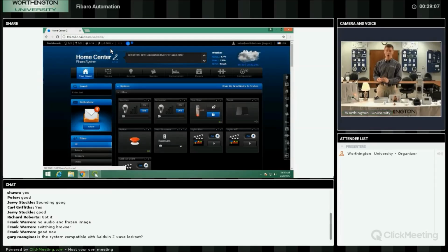So our options when we set this up are, when we have a press on this, turn the light on, turn it off, or toggle it. If I use the on or off, no matter how many times I keep pressing it, I'm just going to have that light go on, if I use the on command. By using the toggle command, no matter what state this is in, we can do the reverse.